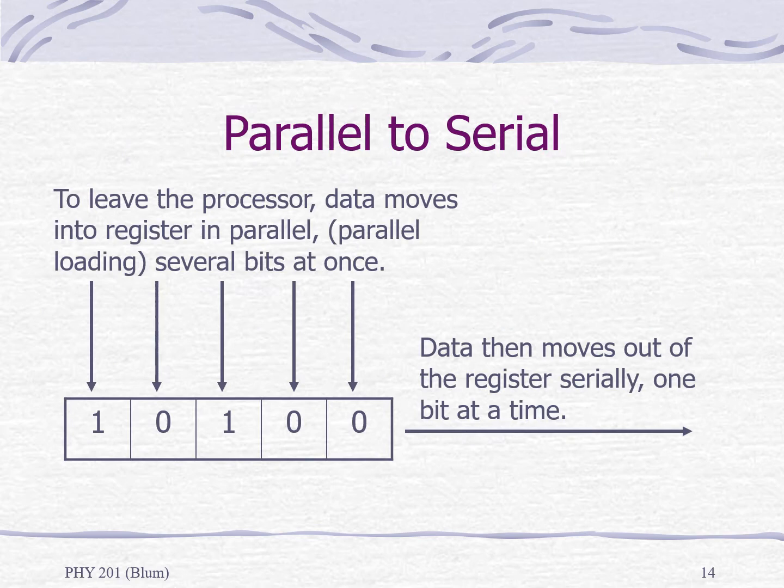If we have a parallel loading shift register, then the data can come into that shift register in parallel, say we're inside the processor, bring it into the shift register, and then we can start the shifting process. And the shifting process, 1 bit at a time, will leave the shift register and then can be placed on the serial connection 1 bit at a time.